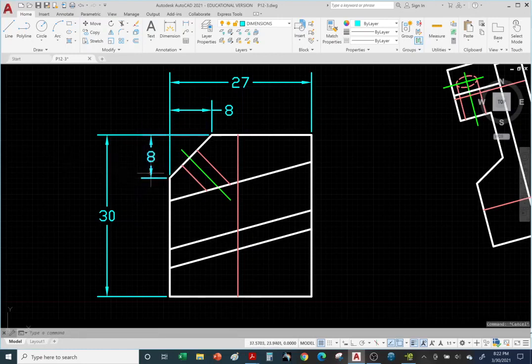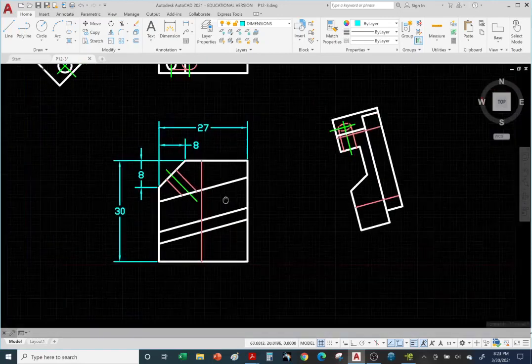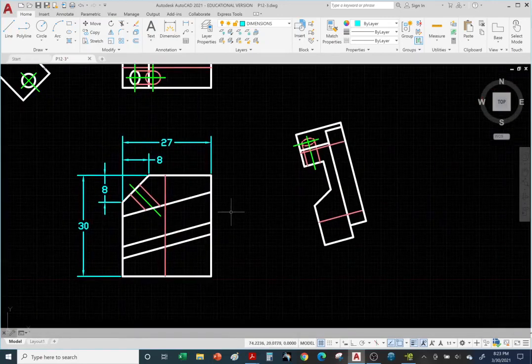And hit escape. Let me move it outward. Okay, hit escape to deselect. If you want, you can move it outward or move the arrows outward. It's up to you. Let's move the arrows. It looks a little too crowded. I'm going to flip the arrows. Just hover over the grip, flip the arrow. And let's flip this arrow and hit escape to deselect. It looks a little better, right? I'll leave it up to you. All right, so let's go ahead and throw in some more dimensions.